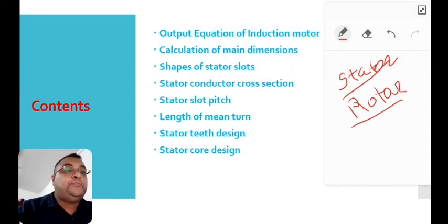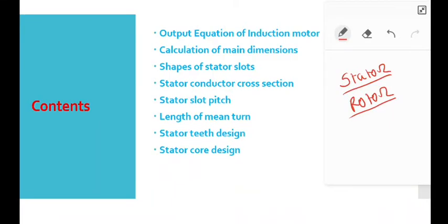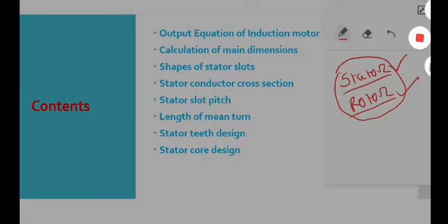So we can say that the AC induction motor comprises two electromagnetic parts. One we already discussed, the stator, which is the stationary part, and the second one, the rotor, which is the rotating part. The stator and the rotor are each made up of an electric circuit, which is usually made up of insulated copper or aluminum winding to carry the current. In both of them a magnetic circuit is there, made up of laminated silicon steel to carry the magnetic flux.